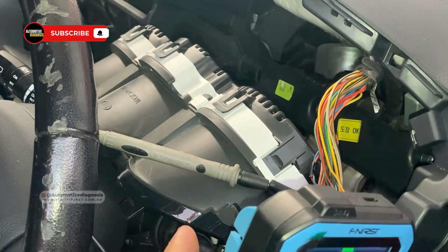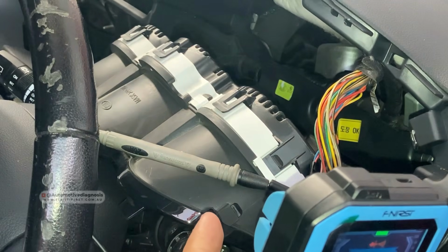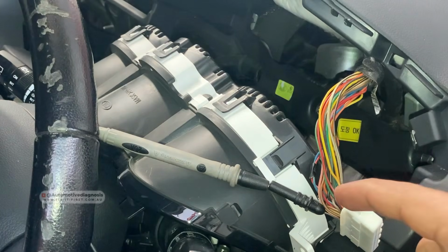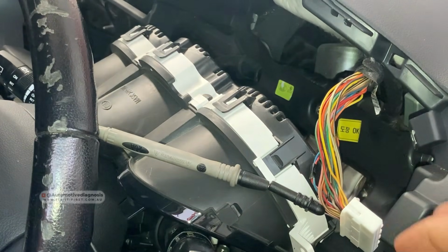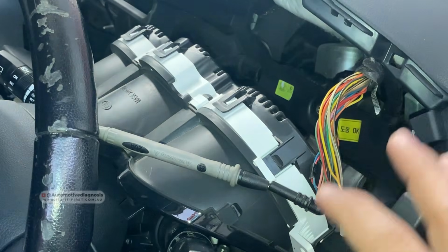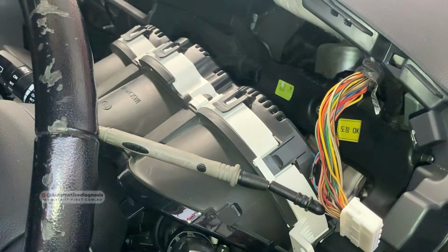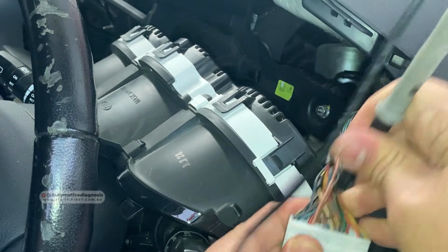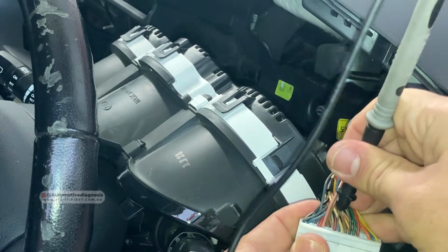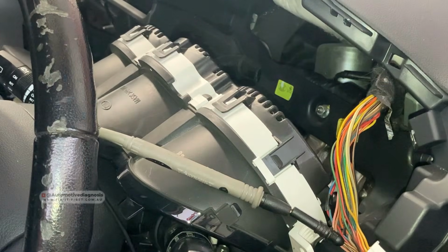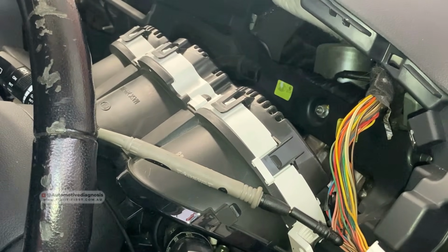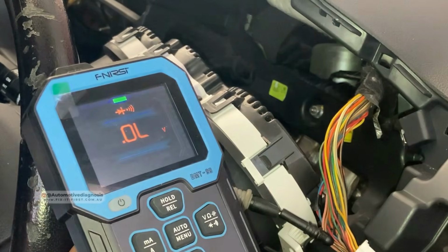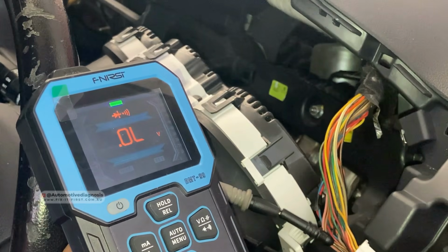So if you do not get any continuity or the resistance value is really high, it means you already found the wiring problem, because you are checking the CAN bus wiring between here and the joint connector. This is how the instrument cluster is connected to the network. And if I go for CAN low, I can just switch this one from here to CAN low, the wire next to that. And on the joint connector, I need to go for pin number 15. I switched the test probe on the joint connector to pin number 15. I'm pretty sure it's easy for you guys to find out.